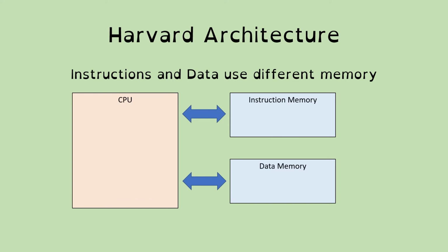There's another alternative, which is fairly well known, not as well known as the von Neumann architecture, which is called the Harvard architecture. And this is where you keep your instructions and your data in different memory, which is in fact exactly what I've said we're going to do, but there is going to be a wrinkle to this. So Harvard architecture has 2 separate memory blocks, and you access them separately.